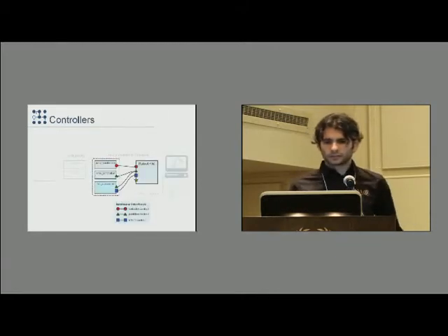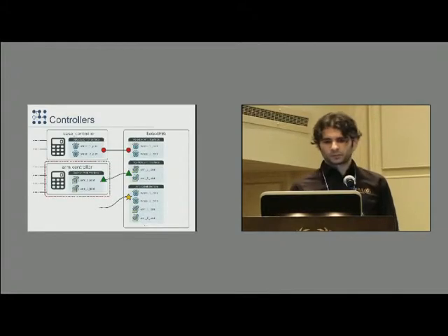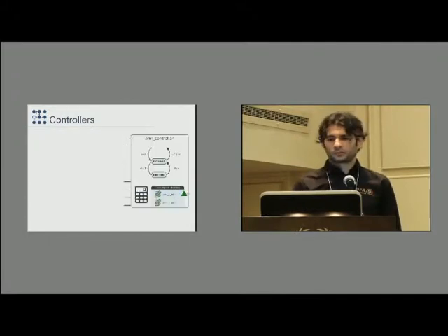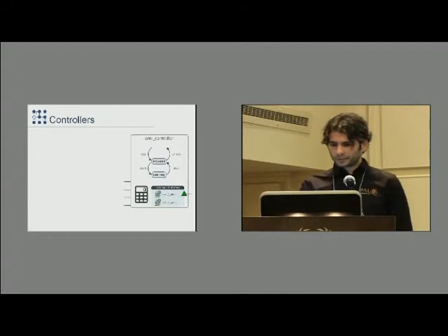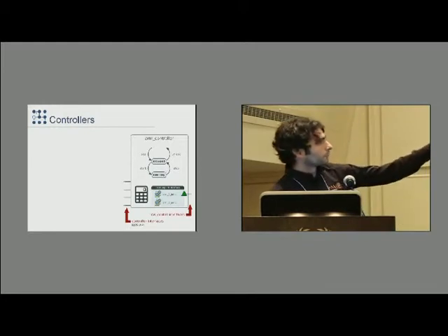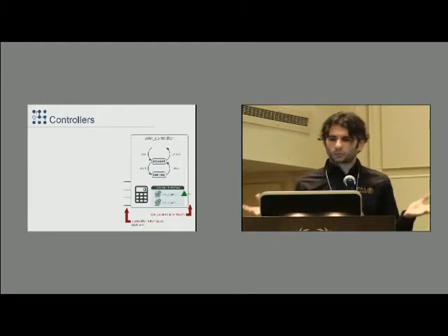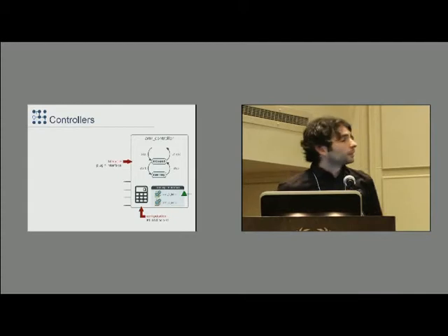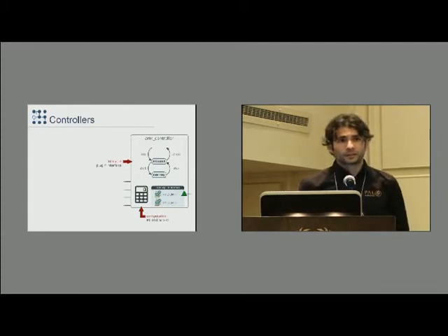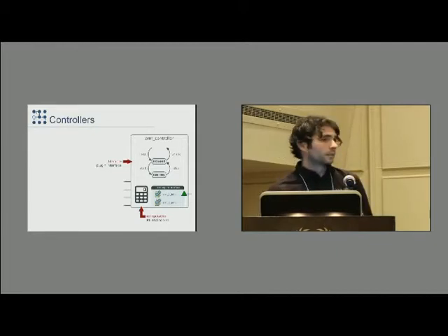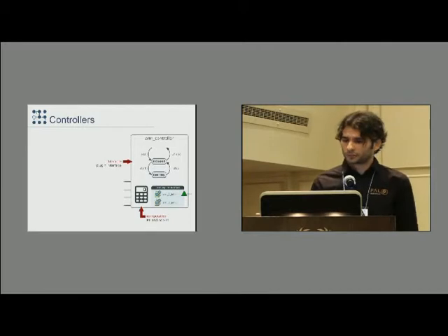So this would be these guys on the left. If we again zoom in on this image, we have the controllers, and what we're going to do is isolate one of them, the ARM controller, and then stretch it out to see more of its internals. Recapping a little bit, on the right the controller requires resources, so there you can see the ROS Control interfaces, and on the left-hand side you see the controller's ROS API. On the top, we have a plugin interface that implements the controller lifecycle. This is a very simple state machine that has two states, stopped and running, and some transitions between the states. And at the bottom we see the computation of the controller, which has two components, one that is real-time safe and another one that is not real-time.